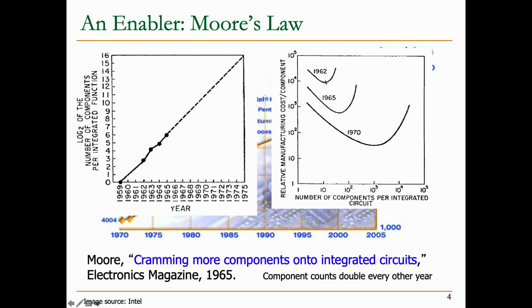And you reach some point where you hit the capacity wall of that chip. You can no longer increase the number of components or transistors unless you get a larger wafer or you scale the technology. By scaling the technology as time progresses, the point where you hit the capacity wall gets shifted.